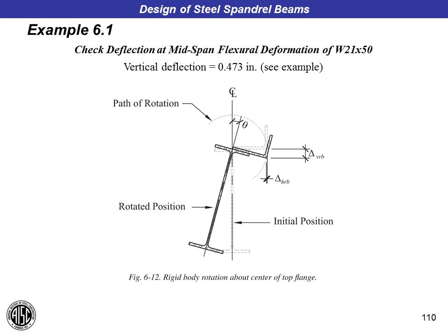So when the deck is perpendicular to the perimeter beam, as it is in this case, I would say the deck is probably adequate to resist the lateral translation of the beam. You're putting the deck in tension in its strong direction. If the deck were parallel to the beam, then I could see that the deck wouldn't be particularly effective at restraining the lateral translation of the top flange of the beam. But on the other hand, if the deck were parallel to the beam, you would have additional infill beams perpendicular to the spandrel that would help restrain its rotation and translation.